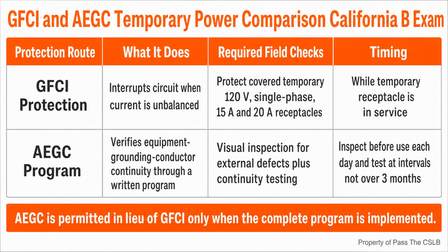California's low-voltage safety rules allow temporary electrical power and lighting at 600 volts or less during construction, remodeling, maintenance, repair, or demolition. The important closeout rule is just as direct. Temporary wiring must be removed immediately when the project or the purpose for which it was installed is complete. That means temporary wiring does not earn permanent status just because it has survived the whole job. If a temporary cord, box, branch, or lighting run is no longer serving the active construction purpose, it should not be left behind as an improvised, permanent installation.